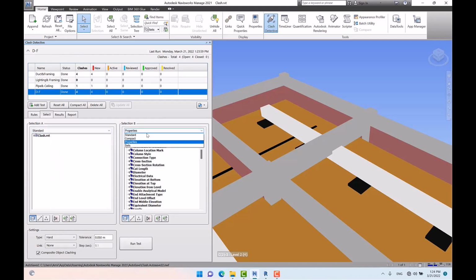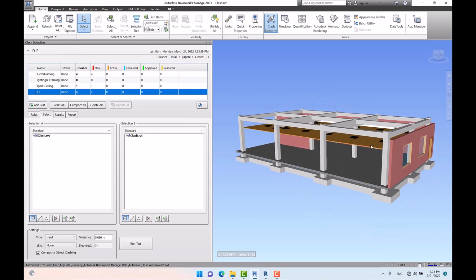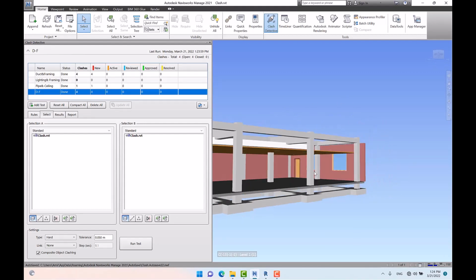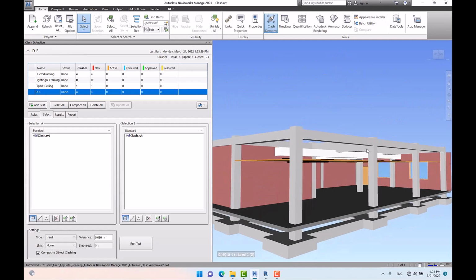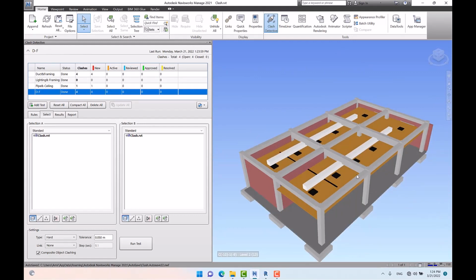I specify a standard for both the test criteria. The third way is usually used for small projects, or in other words, in projects in which you want to take a small group of elements into consideration. I mean, you are not dealing with so many objects. And to be honest, I used it while I was talking about the types of the clashes. Suppose that I want to consider the beams and the ducts, or framing and the ducts, as my clash groups.